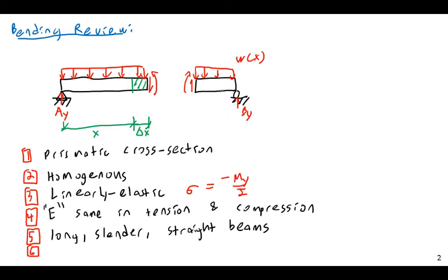What you're really assuming is that if you have, say, a point load, the point load has enough area to distribute that load such that the point load assumption is valid. Again, a point load assumes that the load is applied at a single, infinitely small point. In reality, this is physically impossible. If I could somehow magically apply a true point load to any material, it would have infinite pressure on the surface and just puncture right through even the strongest material, all the way to the center of the earth.